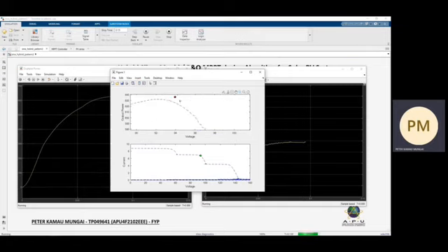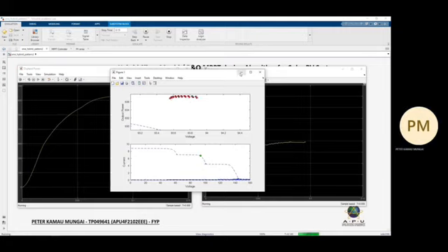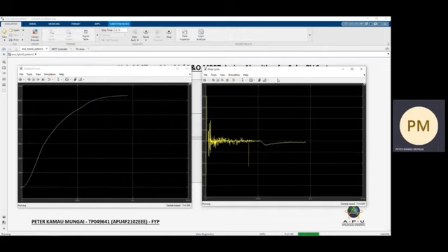And this is a visual representation of the perturbation over an operating point as it tries to locate the local peak. And once the system is done, we'll be able to have a steady duty cycle and a steady output power value. And that is basically the system.